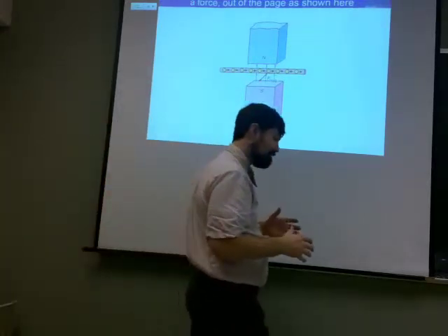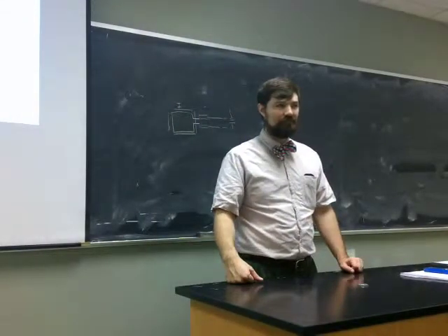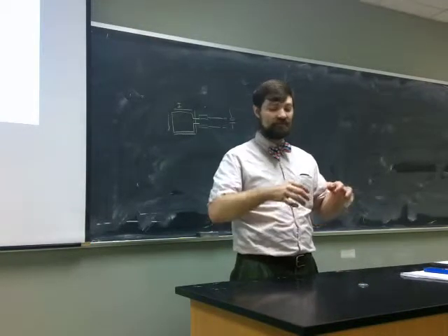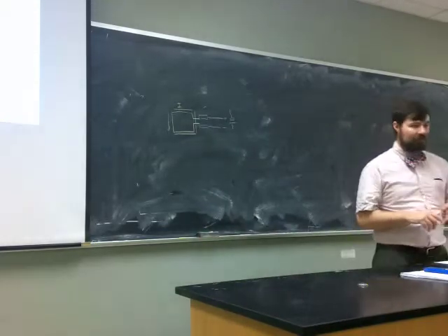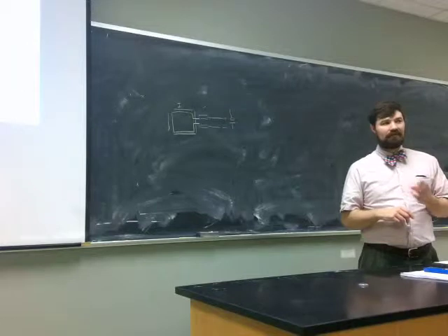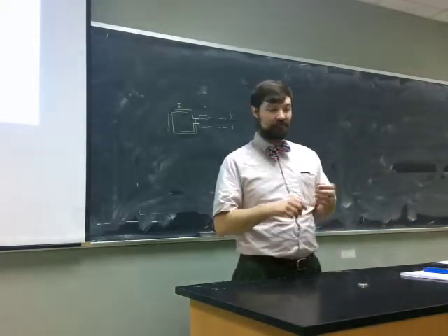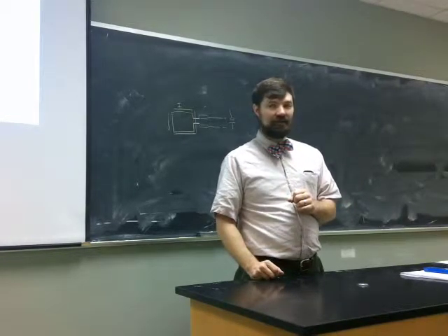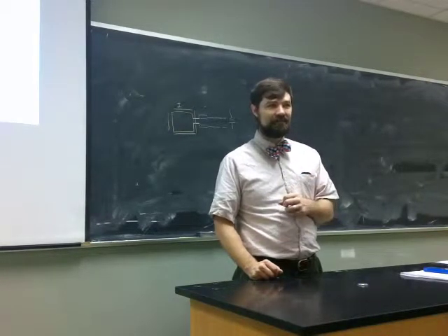You can actually make a simple motor for yourself at home. It's actually quite simple to do. It takes a little more time than I would want to do in class. But all you need is a pair of paper clips, a copper conducting wire, which has insulation that can be scraped, a battery, like a AAA or AA battery works, and a magnet.